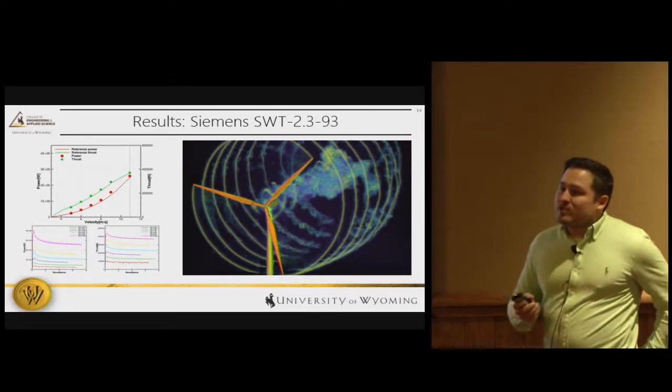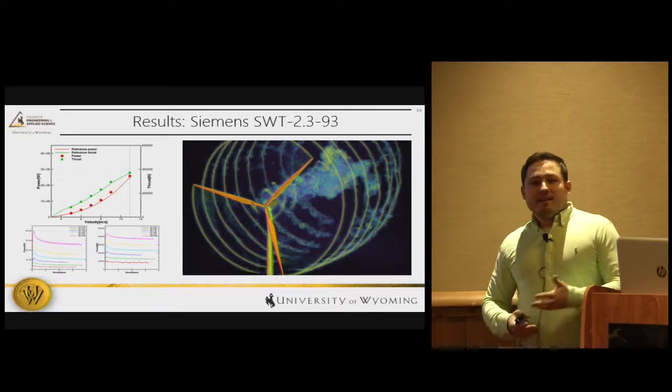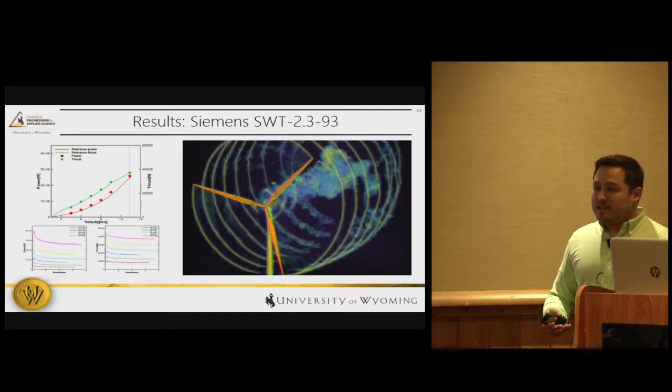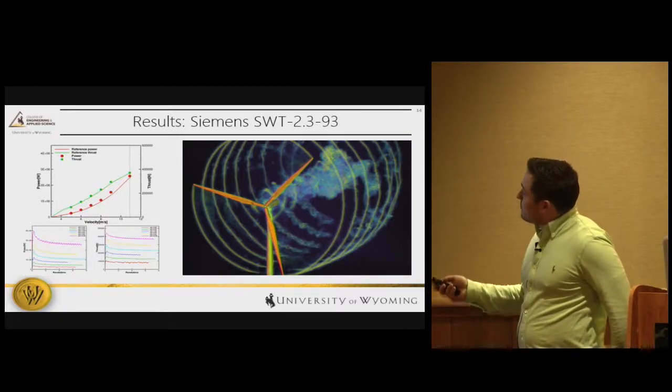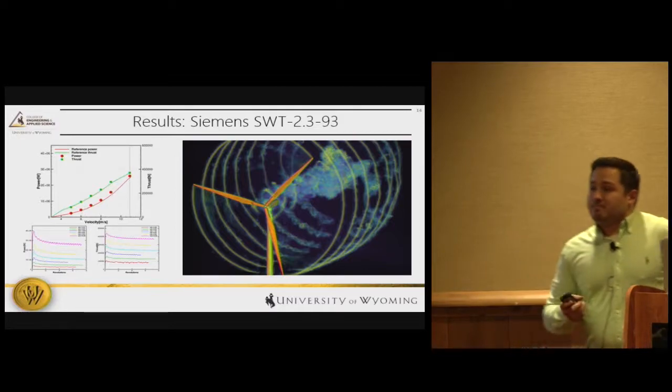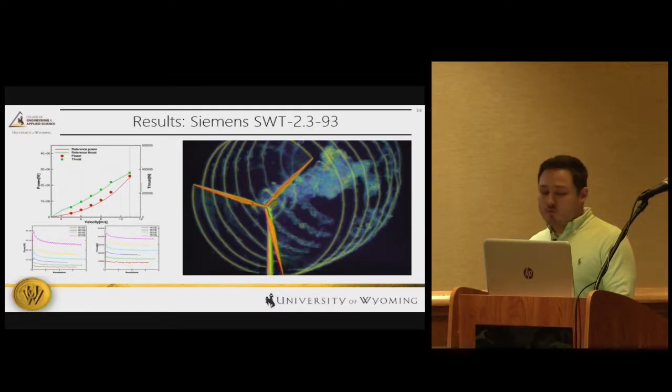You need about 2.2 million grid points per blade. So if you take that, times it by 3, you're at 6.6 million. Add 500,000, you're at 7.2 million grid points per unstructured turbine. Okay? So we're going to use that mesh to scale up this system for full wind farms.